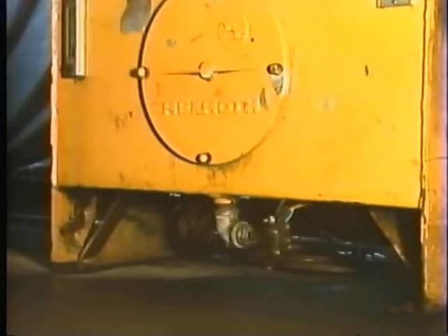If hydraulic fluid has been added to a reservoir more than usual, it's a good indication that there's a leak somewhere in the system. In addition to concerns about fluid loss, operators also need to pay attention to the fluid's condition. It's important to keep the fluid clean and moisture-free to help it last longer and avoid contamination damage to components in a system. One step that operators may have to take to help ensure fluid quality is sampling.